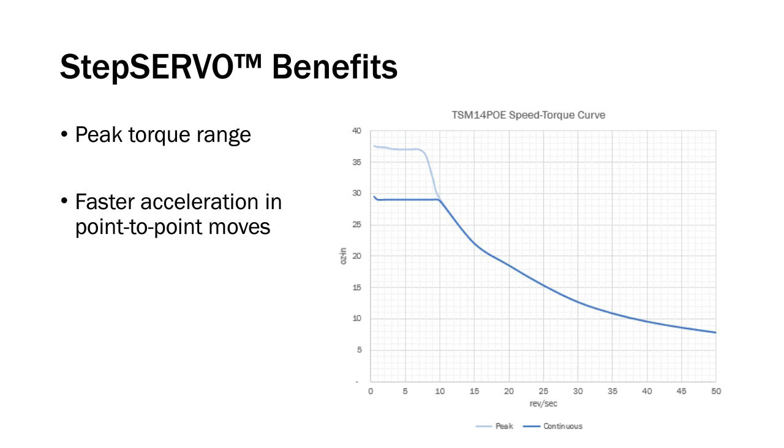So you'll have to play with the numbers to make sure that the number of motors you want to use fits within that budget. I want to correct one thing I said. I said 120 watts. It's actually 25.5 watts at the device, so you'd only be at 102 watts. A 100-watt budget would probably be just fine. Hopefully that answers the question.